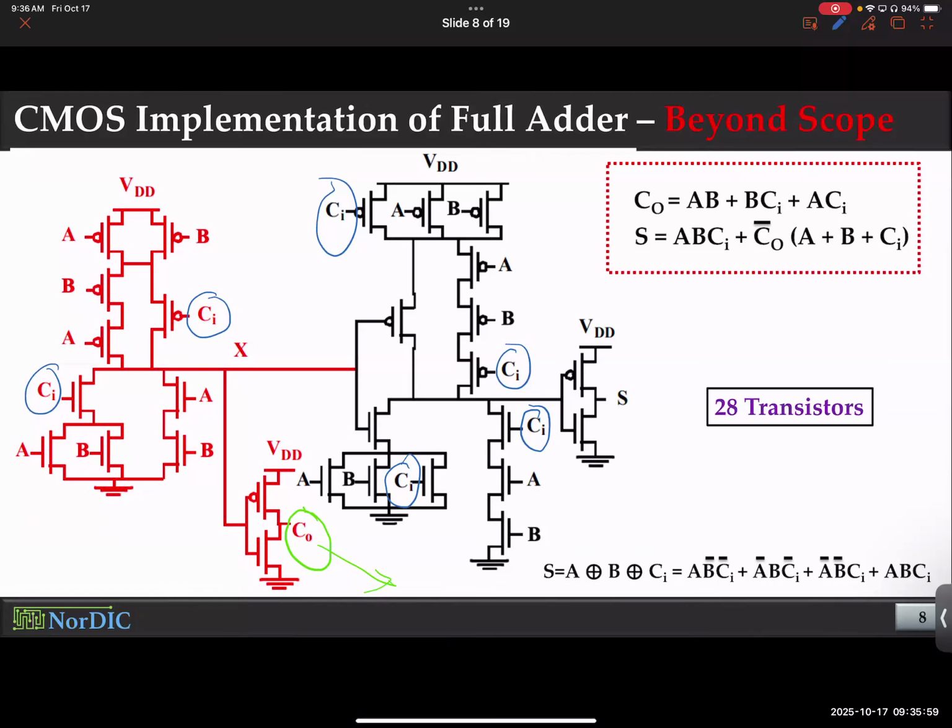Gate capacitors are a concern, by the way. They take more time to charge up or discharge. So you have a single input being routed in 6 directions. You don't have 6 carry in inputs, by the way. It is one input connected to multiple gates. So it is simultaneously driving at least 6 capacitors. Could be more, but at least you can see that in front of your eye.